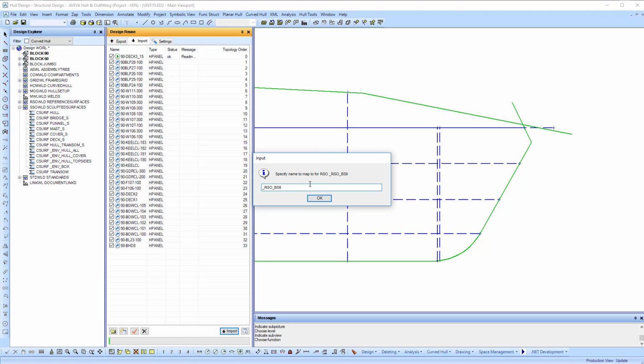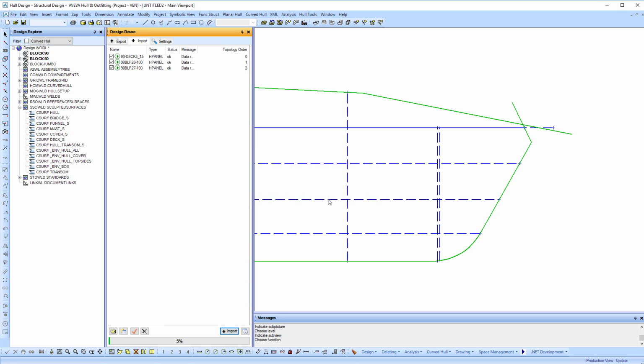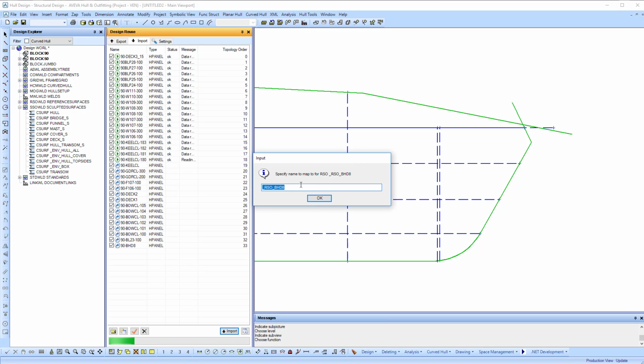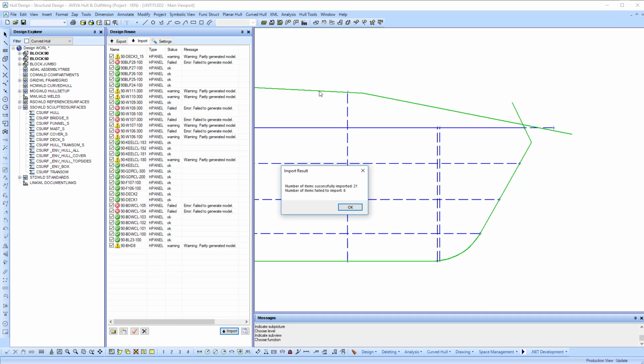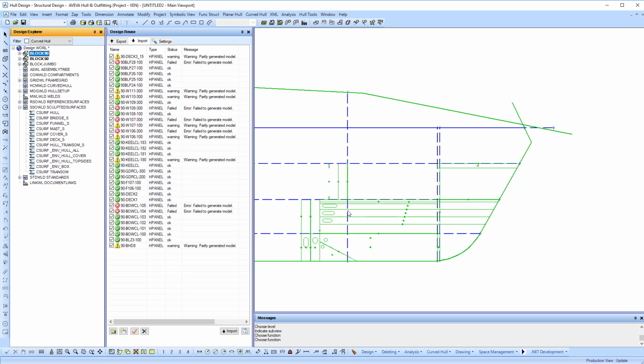Okay, so let's now import that. This was split on block split 8. We'll need to change that to block split 9. This bulkhead will also change from bulkhead 8 to bulkhead 9. So this is a big change, and I'm expecting quite a lot of failures. Effectively what we'll see is the block has been stretched from its original location to the bow. When I draw this, we can see that effect going on here.